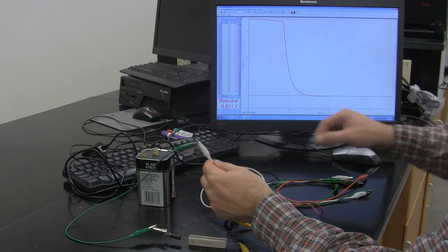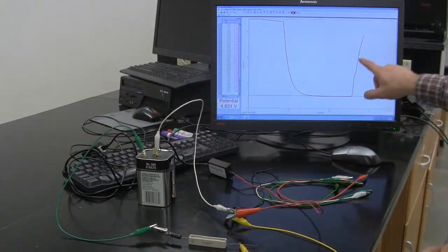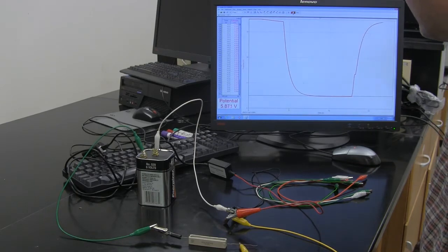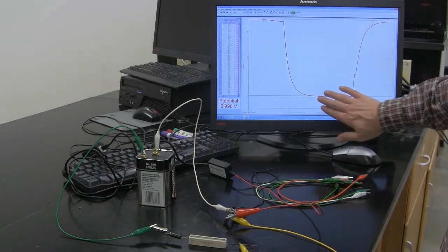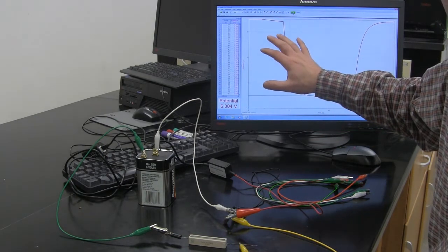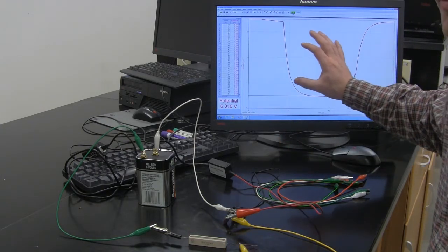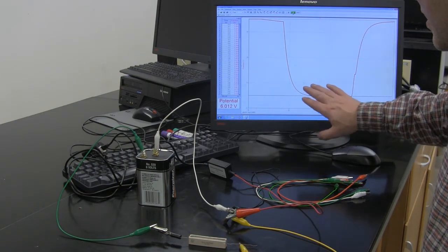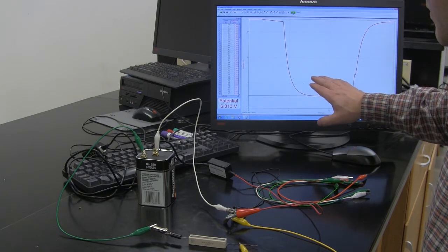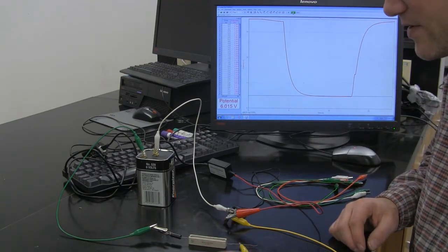And you see it makes that exponential curve. If I wanted to charge it now, I would just reconnect my battery terminals. And I'm charging the capacitor now. And so now I've got this beautiful discharge curve. And I can go into my curve fit. And I can fit that to a natural exponential. And it's going to give me my parameters. And the parameter that's in the exponent of e, the power of e, is going to give me information about the capacitance of the circuit.